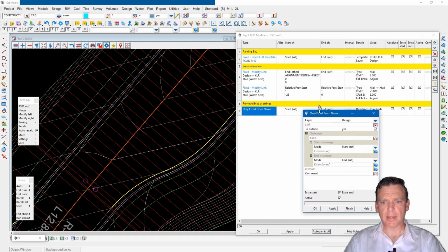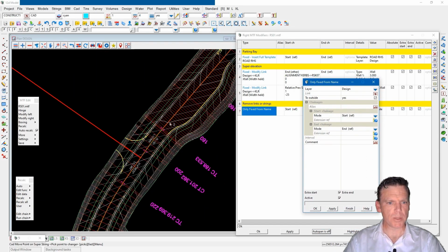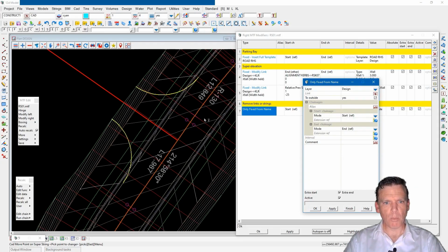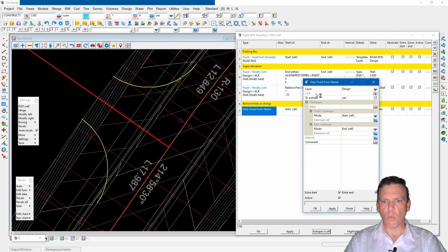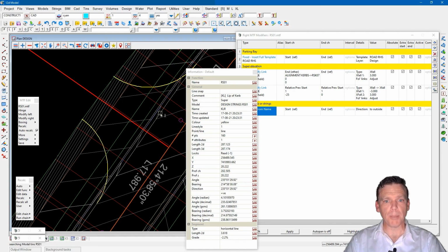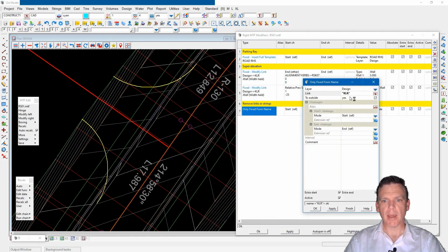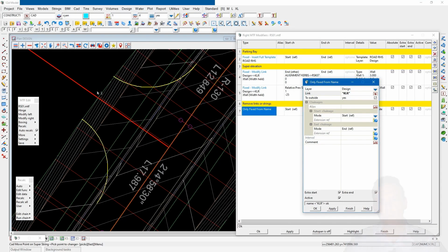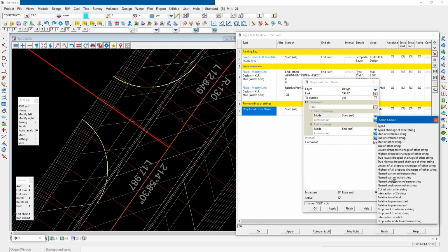So, typical 12D, the panel's set up the same way. It will ask you, okay, what is the link that you want to use? And I'm going to keep that curb lip line, the yellow one there, running through the intersection itself, because that forms up the nice 3% crossfall that I was after. But outside of that, all the links that are reduced will be removed automatically for me. Again, I just needed to tell it where this is taking place.